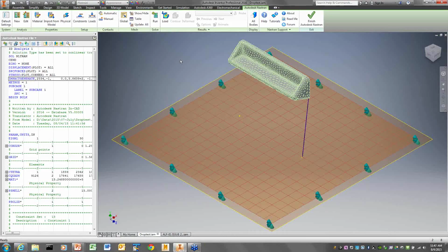The other thing is I'll plot the velocity. I know I can do a hand calc and tell it how fast it should be going when it hits. I can do a little M1V1 equals M2V2. I should be able to calculate how fast it's going to rebound, roughly. So I can look at my graphs and draw some straight lines and make sure that my rebound is about right. And I can often do a hand calc for stress and get an idea whether the stress is approximately correct or not. And those are sort of things I do to validate it.